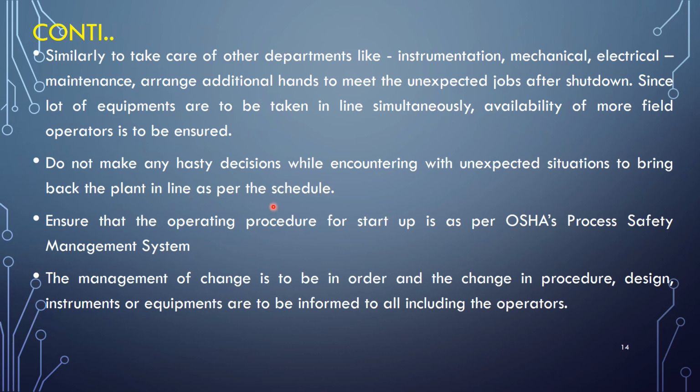Ensure that the operating procedure for the startup follows the occupational safety and health hazard analysis, as per the safety standard. Then the MOC, management of change, is to be in order: changes in procedure, design, as well as instrument ranges, are they changed or not. So these are the things we have to prepare before we go for a startup.